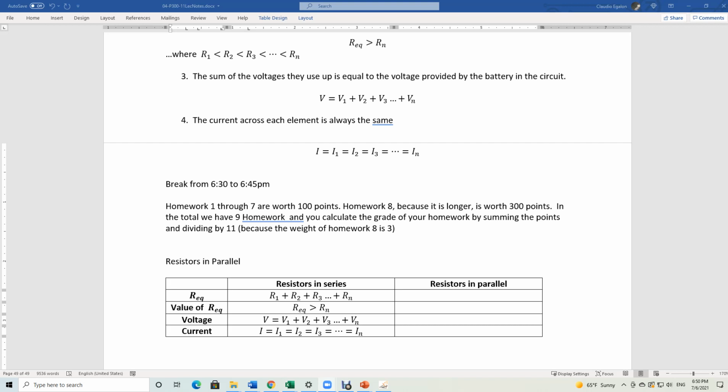That's a very useful device that's sold in any electronic store. I have a bunch of those proto boards here at home. Some time ago I bought like 10 of those. I thought I was going to use them, but I ended up not using them. Here you go. So I want to connect this one in parallel with the other one. I connect here in the same row, so I make sure there is electrical contact between them. So here you go, two resistors in parallel.